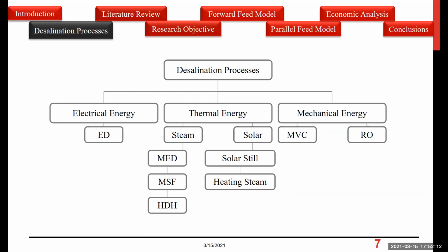This is a general classification of the desalination technologies based on the type of energy that is added. For electric energy, we have electrodialysis. For thermal energy, we have MED, MSF, HDH, solar stills, and even freezing desalination, which takes the energy out, so it's again a thermal system. Then the mechanical systems are basically units operating with mechanical vapor compression, RO, or forward osmosis. These are all mechanically operated units.